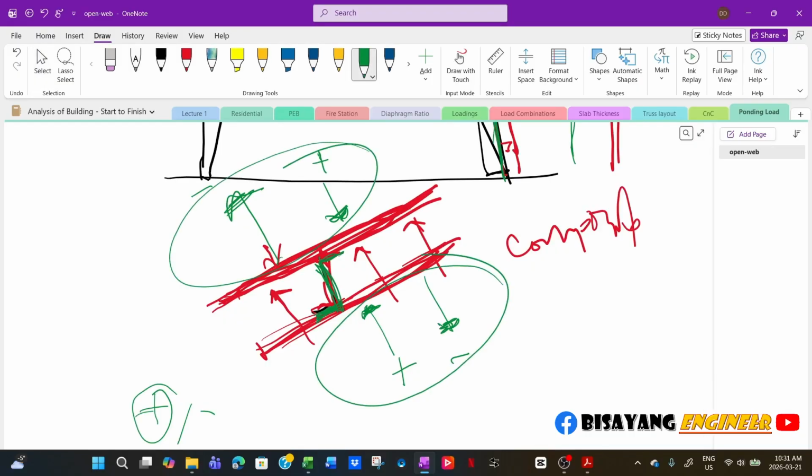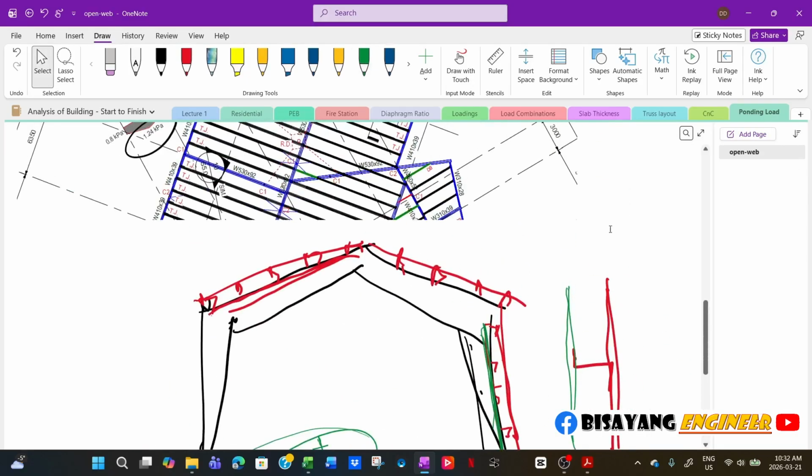So that's why in pre-engineered buildings, you will have to consider both the internal and external pressure. I've seen a post, I won't name him, where the post was about load cases, something like that, with windward only, and then leeward only. There's no such thing as windward only or leeward only. You have to look at your structure, whether it is resisting both the internal wind pressure and also the external one. It will always be the windward and leeward together.